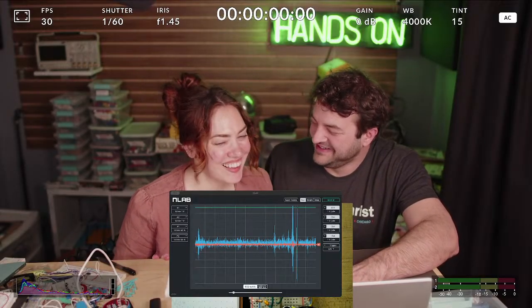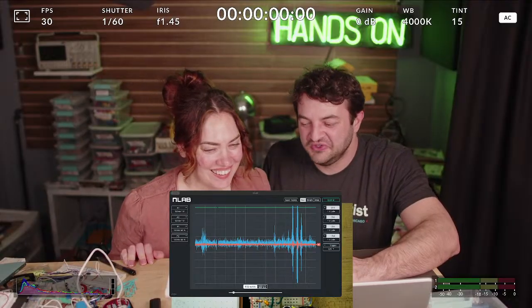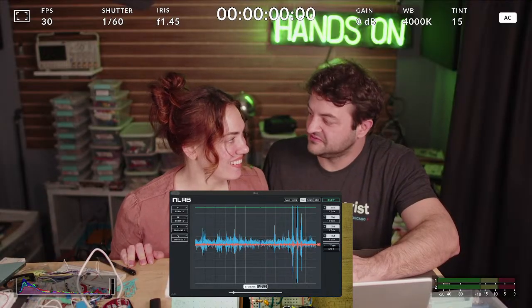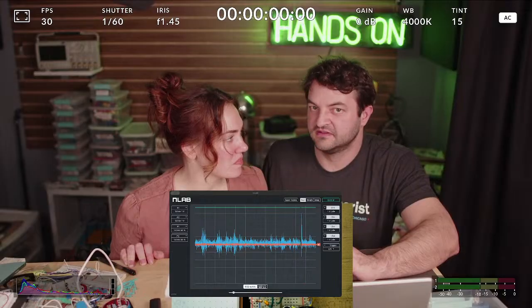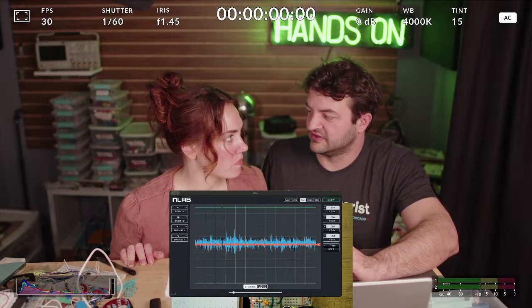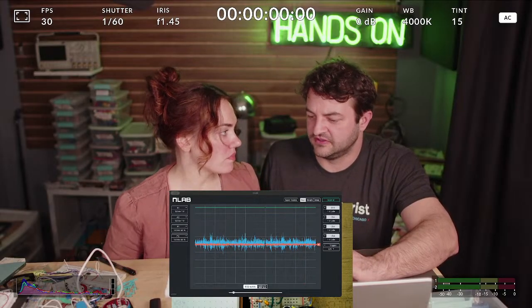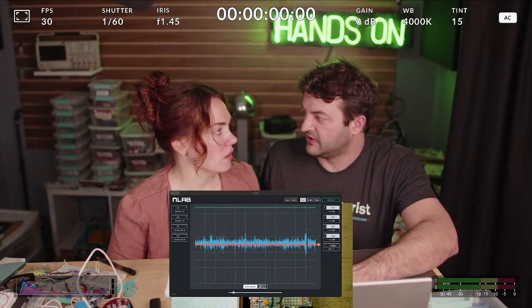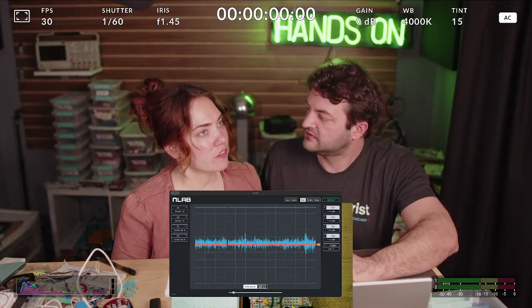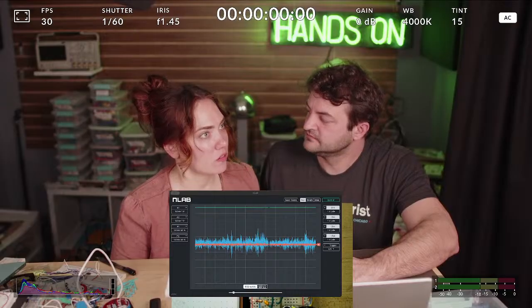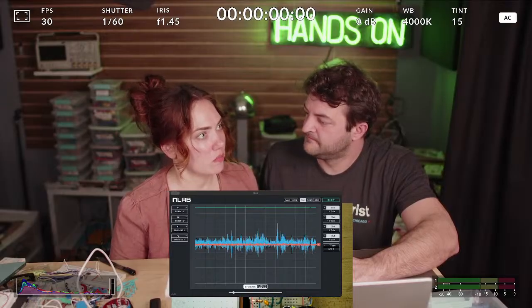Capacitors. You want to probably use a small signal capacitor for filtering small signals. So if the voltages are less than 10 volts, you're probably using 1 microfarad or smaller, using regular ceramic capacitors. Translate that for me. Like in the real world, what would small filtering look like?